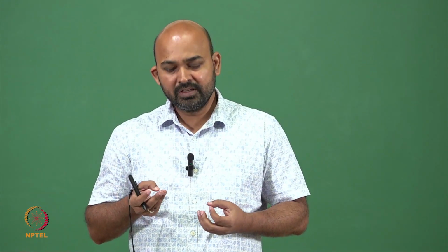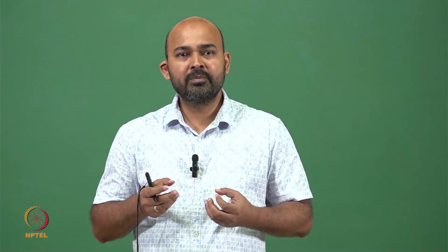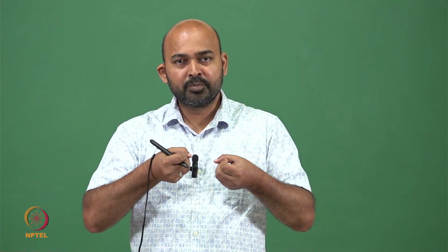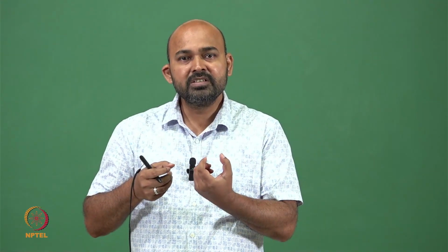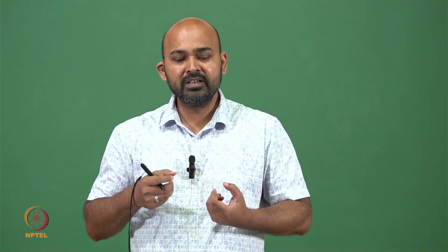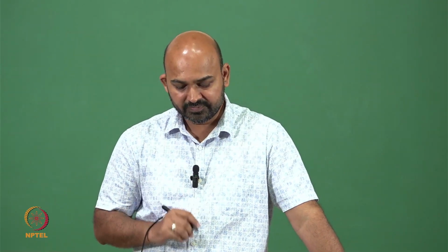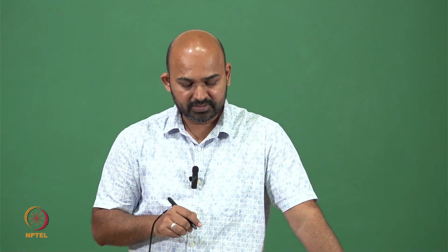So measurand can be temperature, which can thermally expand the optical fiber, or it can be force, where we are applying a force which can pull this fiber optic sensor, and there is a change in the distance between the grating. It can be pressure, it can be multiple other measurements which we can use to make sensing using these fiber grating based sensors.